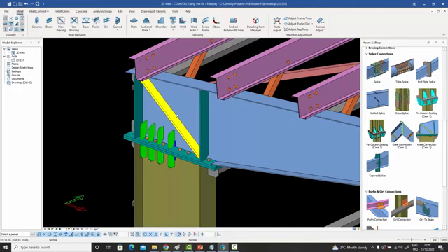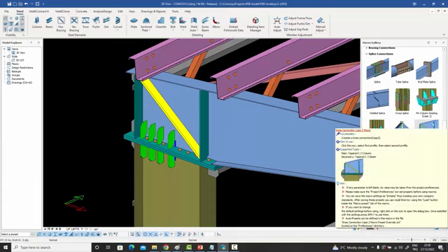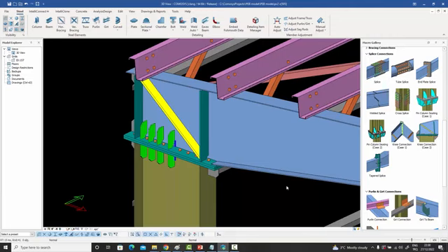And the good thing about this is that instead of 3 different macros, all of them have been collected into this one single macro, and within that macro you have these options of creating this diagonal stiffener or doubler plates, or basically the removal of the web and insertion of a thicker plate to take care of those high stresses. So this is a very important macro which we've added. It's called the knee connection, and it is there for, like I said, the pre-engineered building sector.